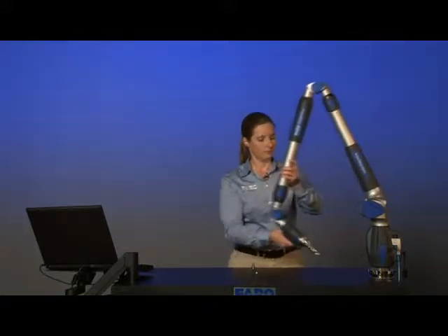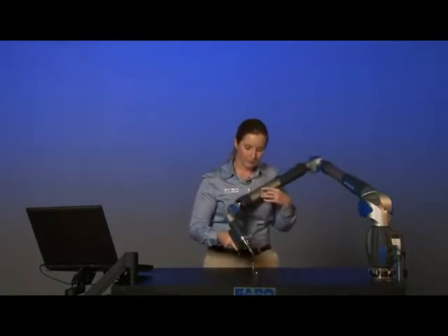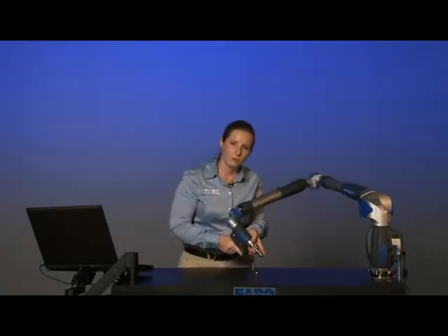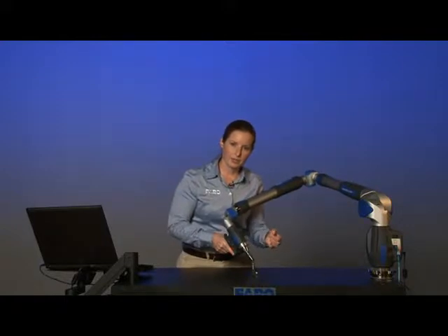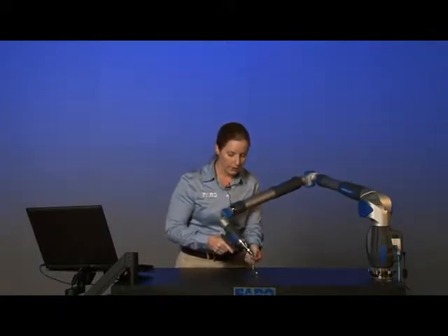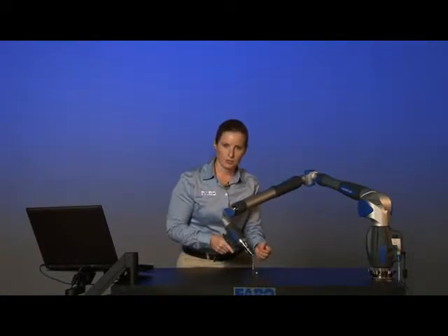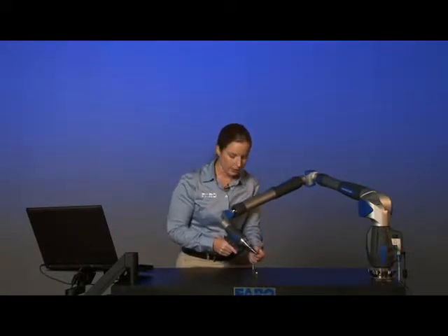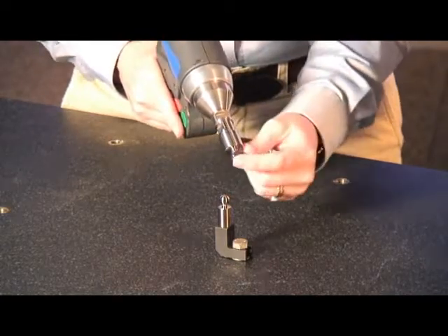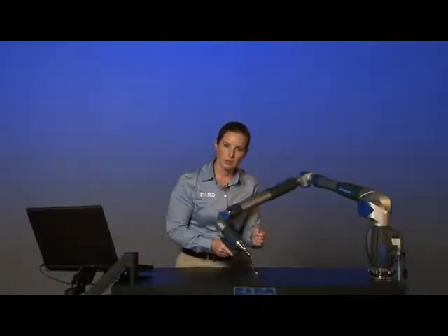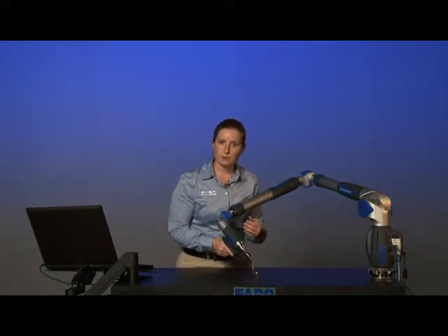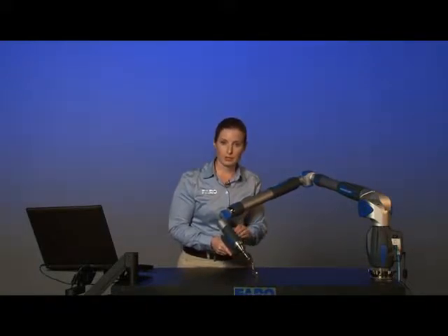Now that we have the software set to calibrate the probe, we're going to bring the arm down and calibrate on the calibration sphere. For the swivel probe, we're going to do a standard sphere calibration in which we touch the ball of the probe to the ball of the calibration sphere. It's important as you're calibrating to make sure that you're touching the spherical surface and not the cutout surface to the calibration sphere. We're going to take 44 points in 4 sets of 11.